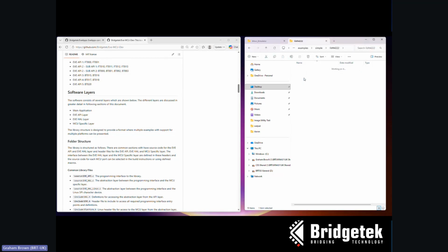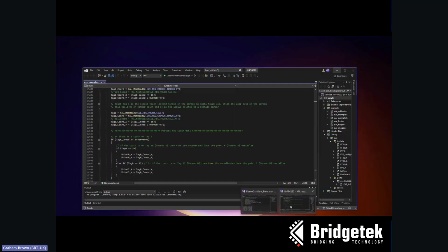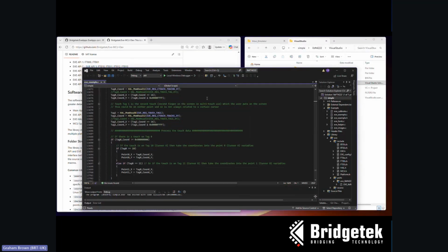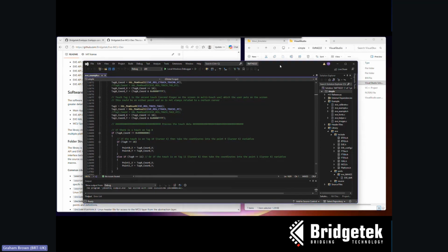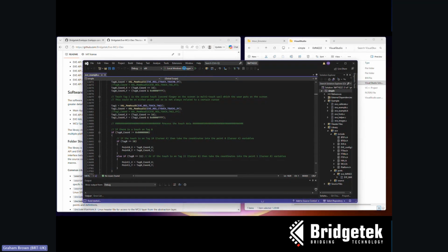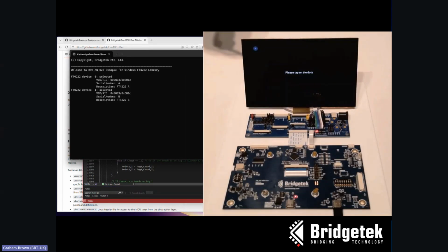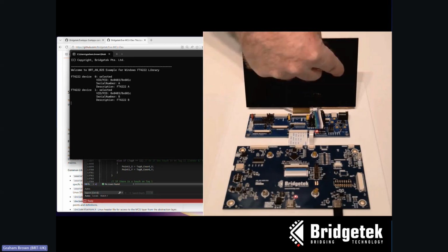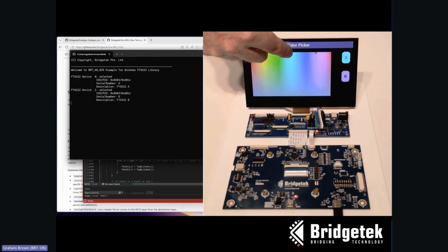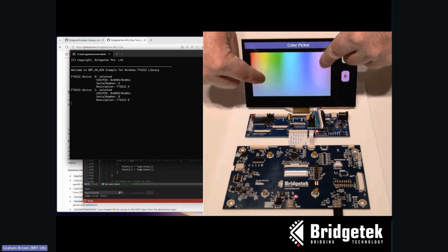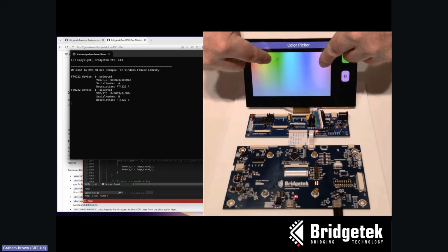Here we use the USB to SPI FT4222 build of the code via Visual Studio. We can open the solution here, and we can see the main EVE example.c file, which is this part shown as the touch handling. Once we run the code, we can see EVE's built-in calibration screen coming up. And once we've done that, we can see a square colour picker, and we can interact by moving each of the 2 points individually. We can also use the multi-touch features of the BT817 to move both together, and indeed we can move up to 5 points together.